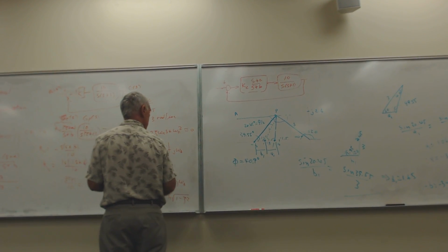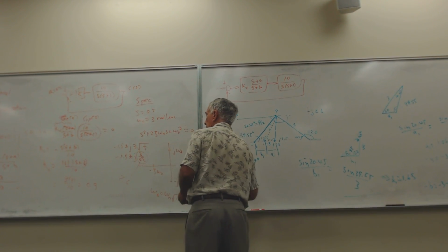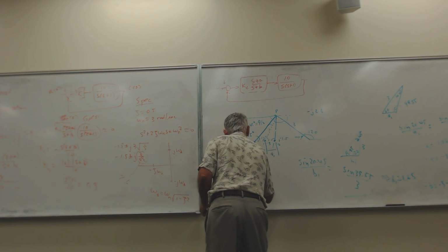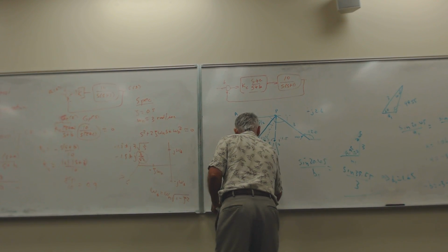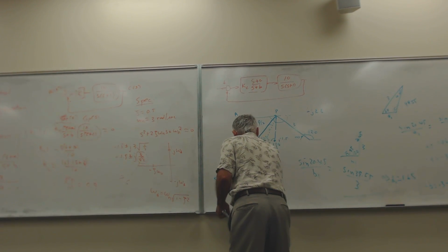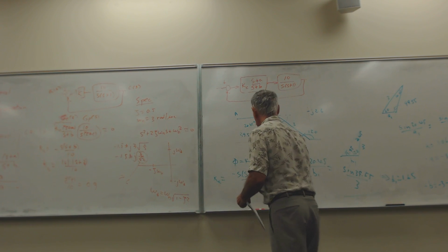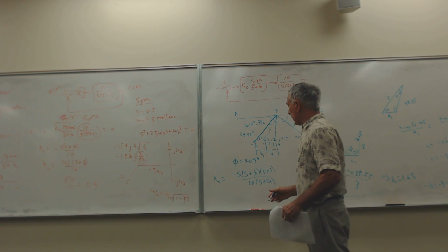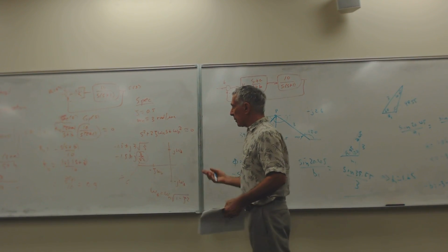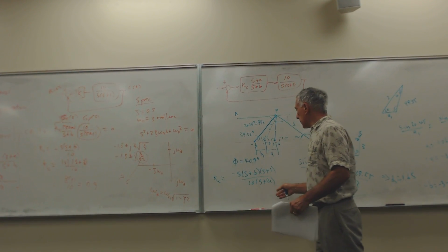So the expression for K of C is going to be minus S plus B, S plus 1 divided by 10, S plus A. So if you know A and B, we can substitute in this desired closed-loop transfer function pole, either one, plus or minus j2.6, into this.